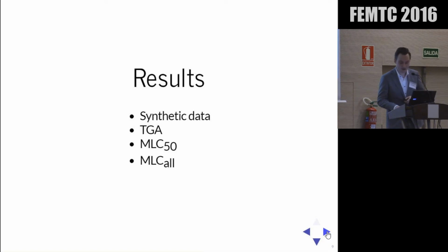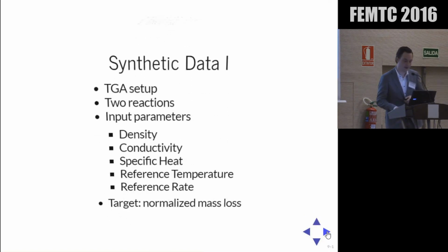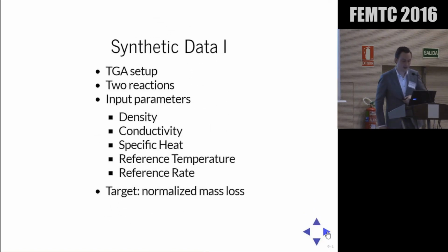And let's now come to the results. The synthetic data was a TGA setup. We used 2 reactions as input parameters, used density, conductivity, specific heat, reference temperature, and reference rate specific to FDS. And our target was the normalized mass loss.